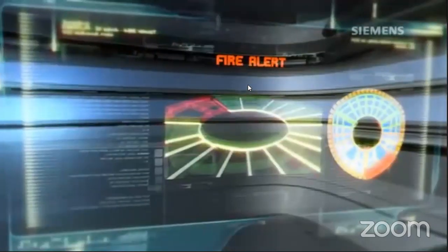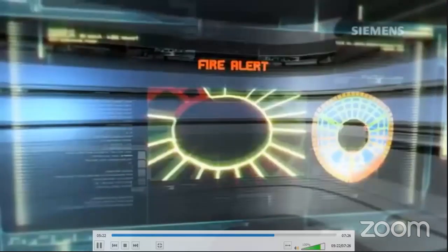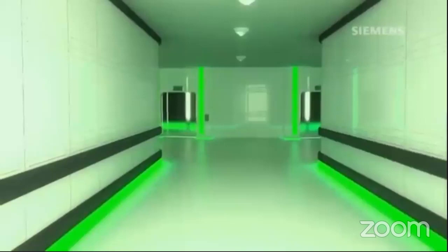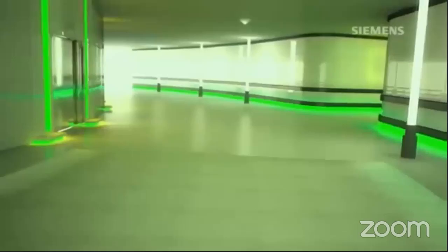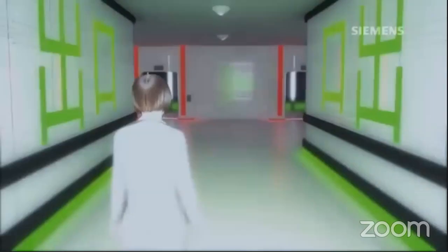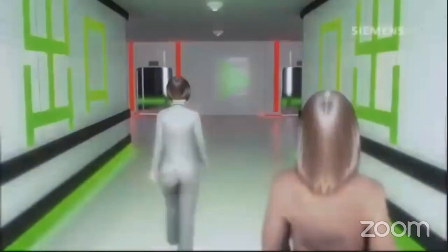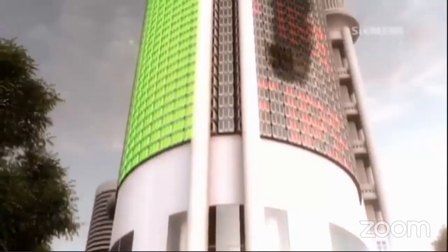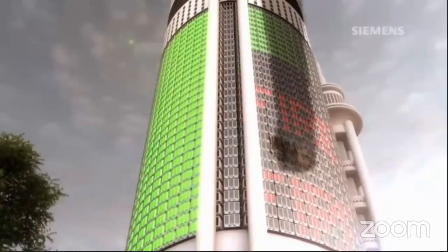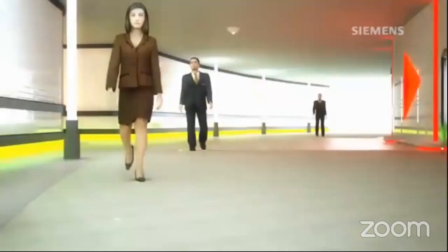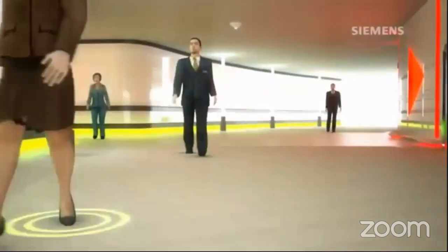Occupancy sensors in the lighting system do more than just turn the lights on and off. In an emergency, they also assist in organizing a fast, orderly, and thus safe evacuation. Escape routes are defined according to the situation. Lighting installations operate in emergency mode and point the way dynamically. Acoustic signals and voice prompts provide additional support. Subsystems support the evacuation scenario. Intelligent systems help detect flows of people and separate them when escape routes are about to become overloaded.